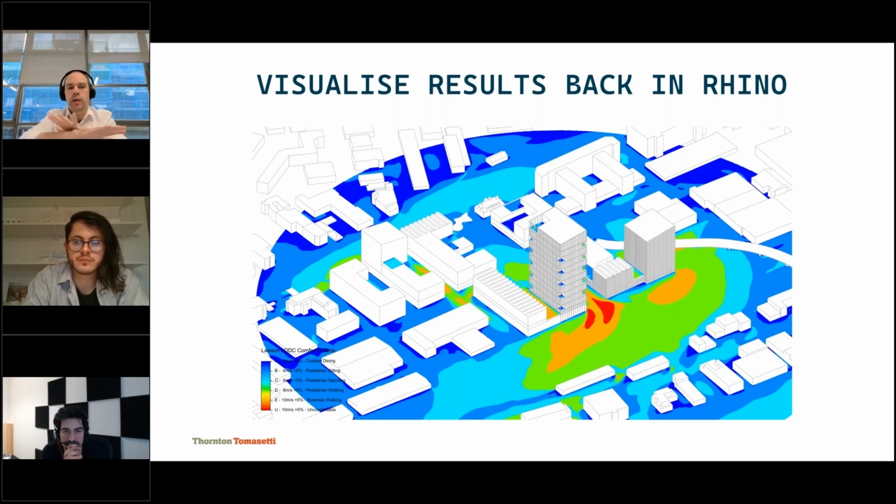So for instance, we looked at typically a 1.5 meter high plot around this building, plus the roof terraces as you see there. And then you can see the effects of the wind really hitting this tower, downdraft, and creating those uncomfortable conditions on the ground.